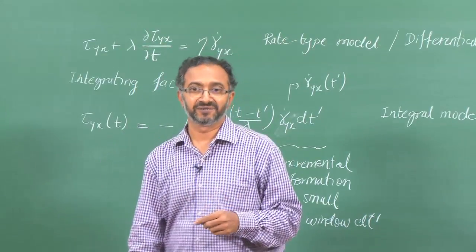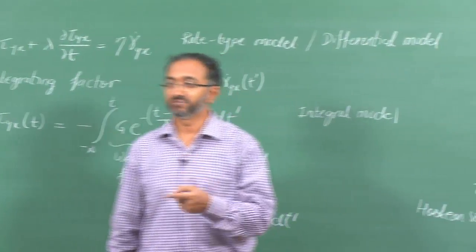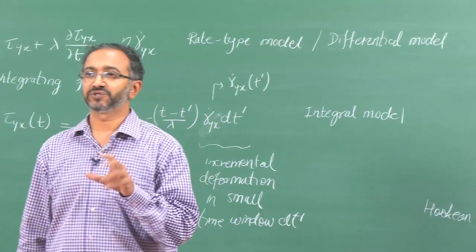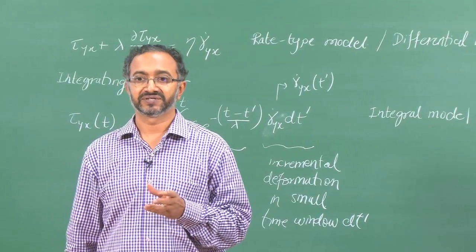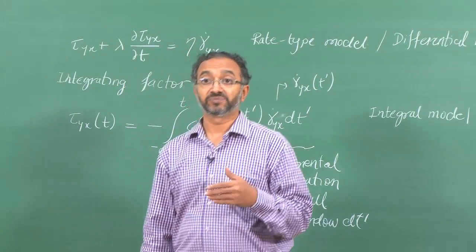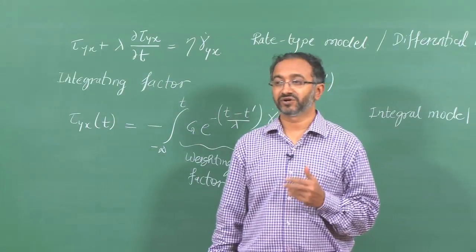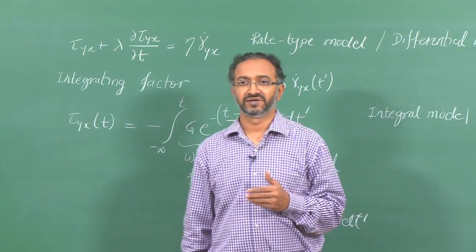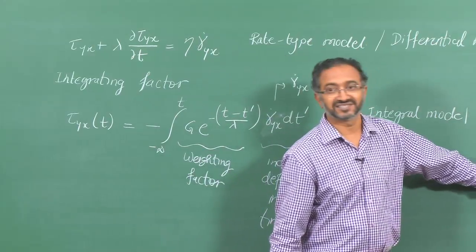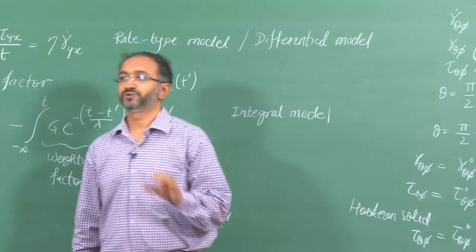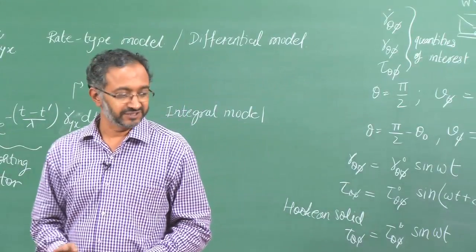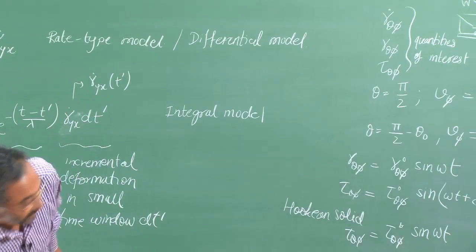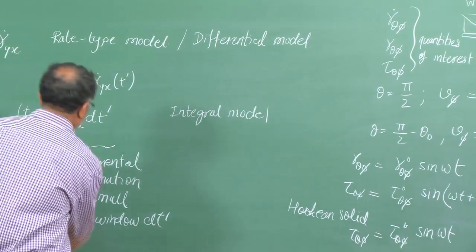Only for linear systems, whatever frequency is being used to provide a stimulus, the output is also at the same frequency. Otherwise, generally we will observe higher harmonics for a nonlinear system response. So, as soon as I have written this, it is also assuming linear response. Within linear response, this is a completely general expression. And so, now